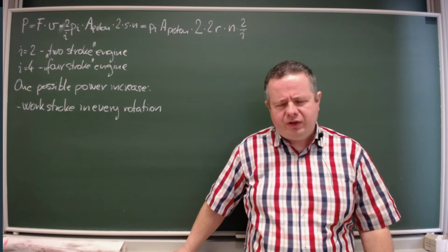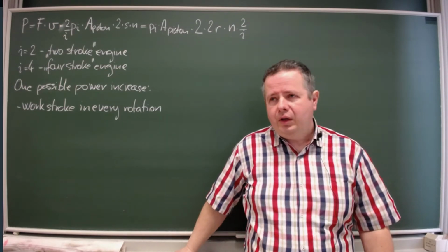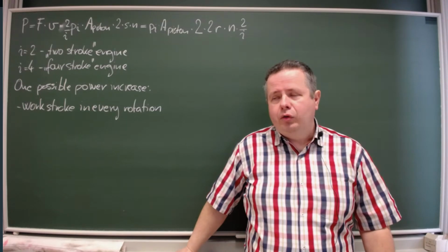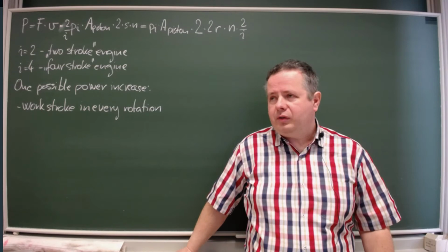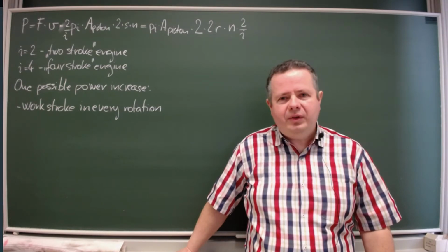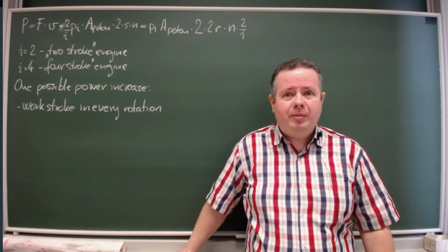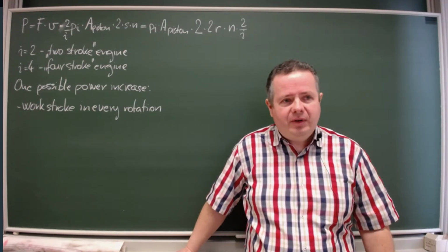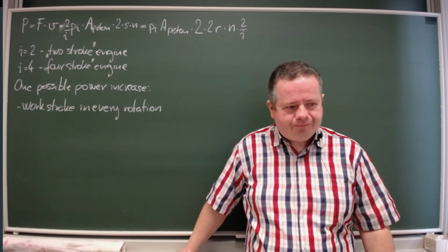So in the 4-stroke process we get admission, compression, work stroke plus exhaust, but it needs 2 complete crankshaft turns. What to do if I want to have just one crankshaft turn for that? I've got to put something elsewhere. And this something can be the admission, this can be the compression, or any other possibilities that I will enumerate shortly.